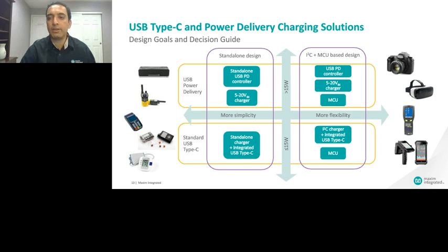And as the standard becomes more and more popular, there is also the push to have the power delivery standard, which is also standalone now. In this case, we have products, which I'll go through in more detail later, with standalone operation and a USB power delivery controller, which performs all of the negotiation and control for you. You also have a charging block which performs wide input voltage range, high efficiency, and very high performance charging. In this case, you may have applications such as two-way radios or set-top boxes and so on.